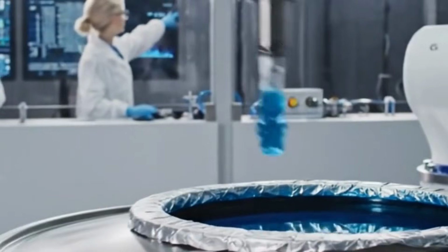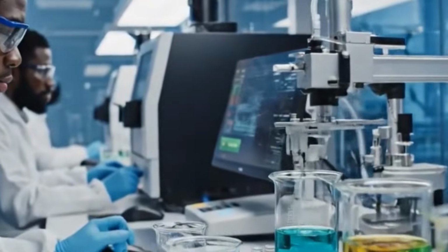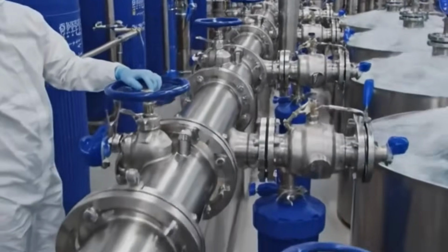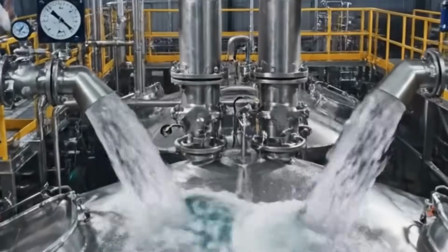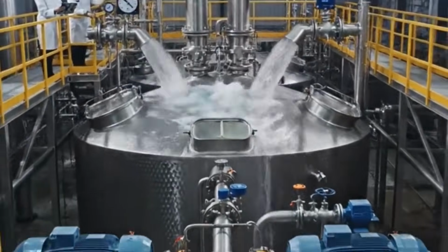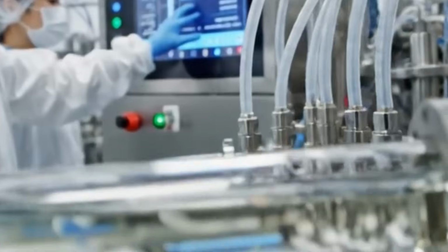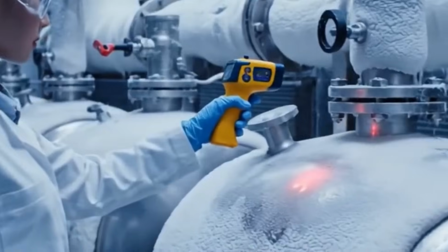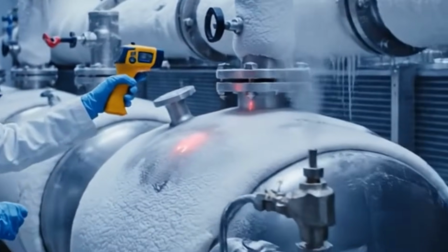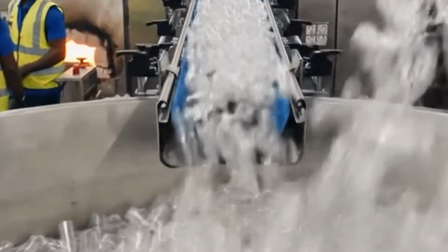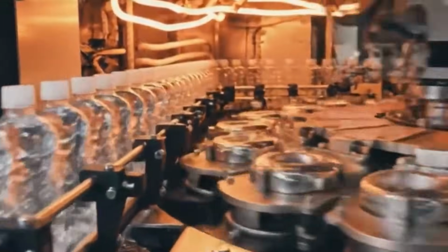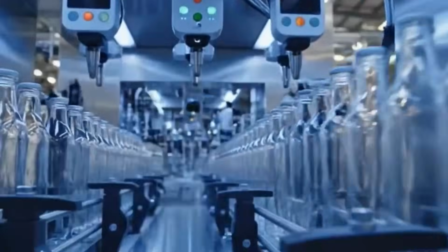Fluoride compounds, such as sodium fluoride or stannous fluoride, are prepared as pre-dissolved concentrates in separate mixing tanks using deionized water. These are dosed into the main batch at levels typically ranging from 225 to 1000 ppm fluoride ion. Addition is done slowly to avoid precipitation, and pH is adjusted immediately afterward to maintain stability.